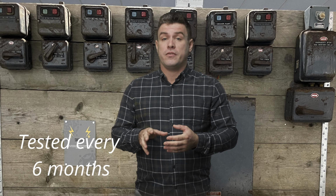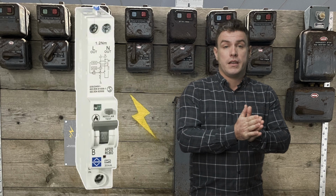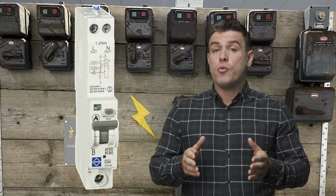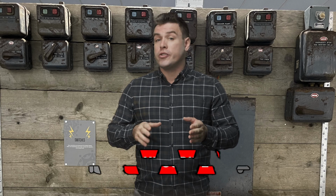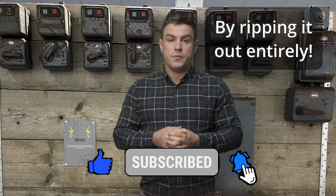Modern consumer units accept a combined residual current circuit breaker with overload protection, or an RCBO. The big advantage to this is it only affects the circuit that's at fault for all of the conditions that we mentioned above. These are a good upgrade. No doubt I'll be upgrading my fuse board at home once I'm qualified with these.